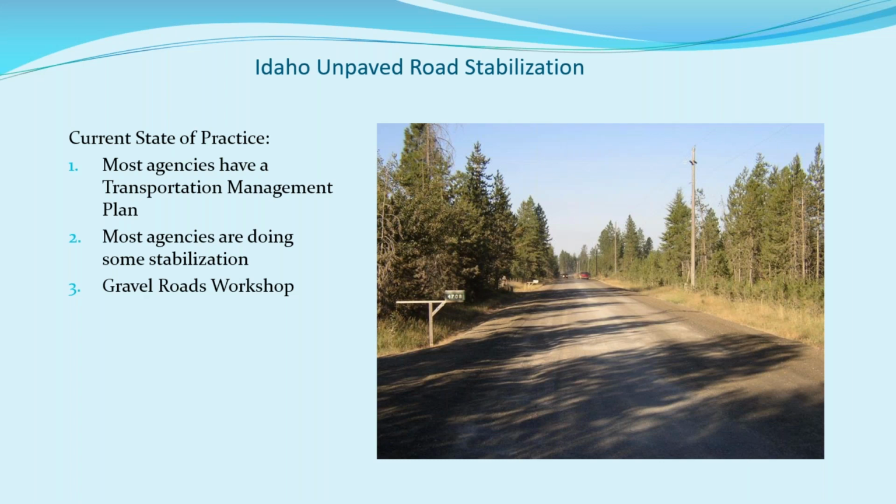We'd have the operator of the jurisdiction that owned that roadway grade it, but then we'd show them how to check their slope, make sure they got the right crown in it, make sure that they have enough water in it. And then towards the latter part of the day, we'd actually come in and put some stabilizer on it, usually a mag chloride type of stabilizer. We'd do about 3 of these workshops a year in different locations around the state. We had this program for about 3-4 years. And that's the reason I say most of the local jurisdictions here in Idaho, on their most heavily used unpaved roadways, they use stabilizers.